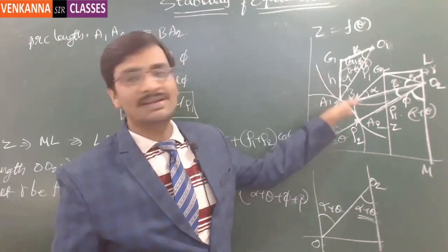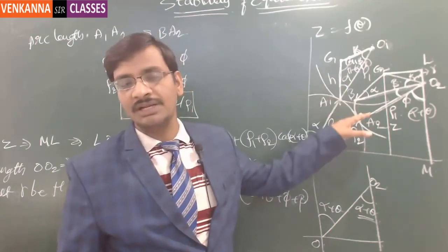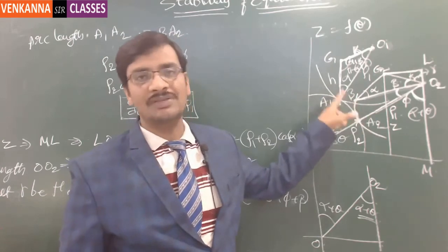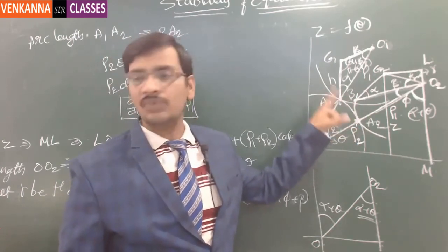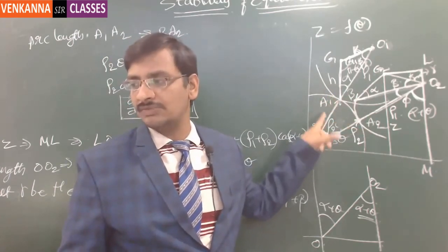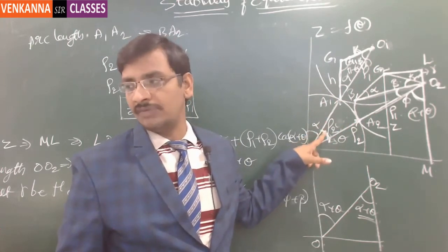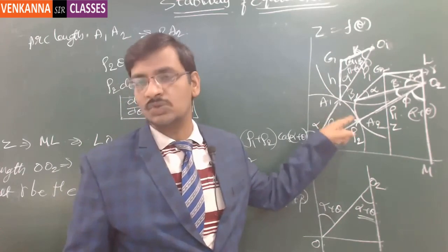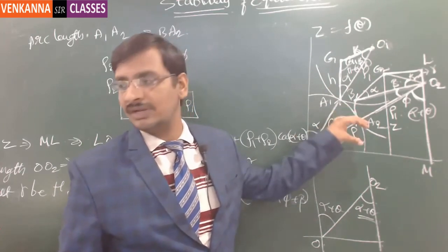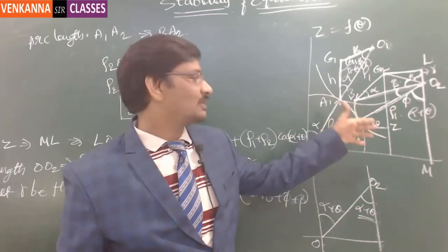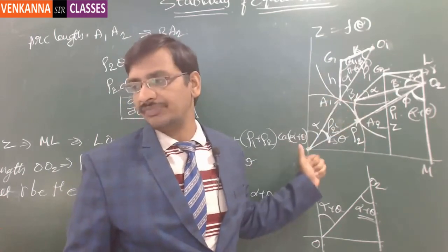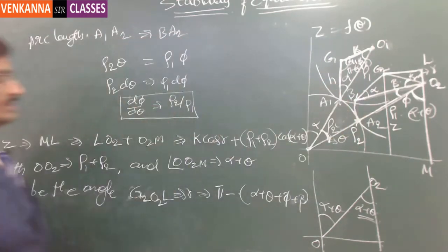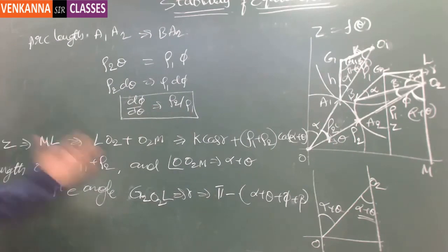Now you have given a little displacement. Why we have given this little displacement is, you wanted to express the z value in terms of the variable theta, so that at what value of theta it is going to be an unstable condition. That's what you wanted to identify. For that you have given a little displacement so that you can express the z value as a function of theta. For that we have done all these things. Got it? First you note down this. Now we will come back to the derivative of z.